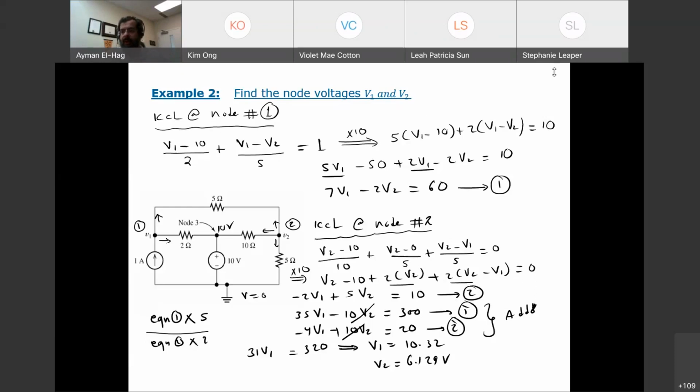So let me see here. Rahmin, Waqar: the equation is not fixed and depends on the location. There's nothing called fixed. It depends on the node and the resistors, so we will have different equations. However, what I'd like you to practice, and keep this in mind, is to always assume the currents are leaving. That will make your life much, much easier. Okay?